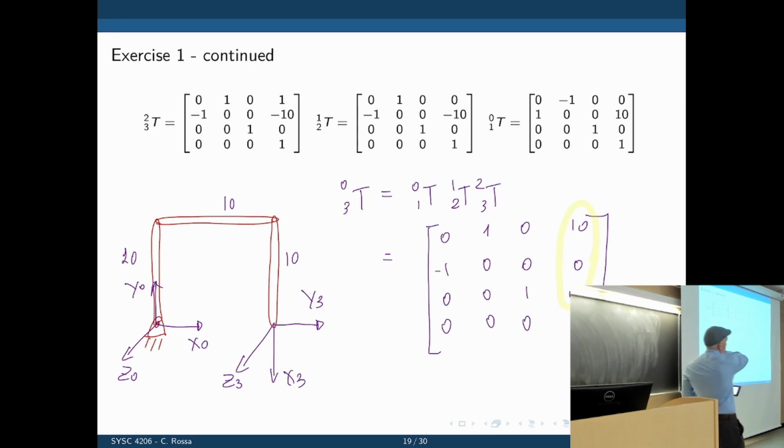The entire robot would be aligned in a line like that, so all the axes will be pointing towards the next joint. So x0 is pointing towards this one when theta is 0, because now it's 90 degrees. So when all thetas are 0, this robot is aligned like that. So x always points to the next one.